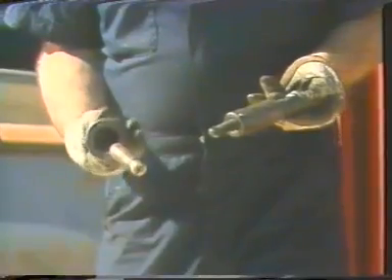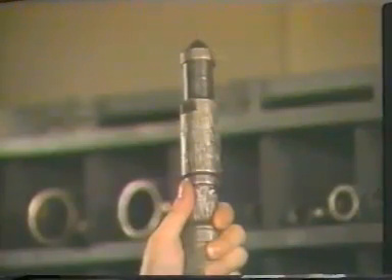For larger diameter wire lines, another type of wireline socket is used. With this type, a wedge and a thimble are used to attach the wire line. The wire line is bent around the wedge and pushed back into the thimble. The body of either type of wireline socket is machined with an external fishing neck flange, which allows latching and retrieving the tool string if it should become lost in the well.